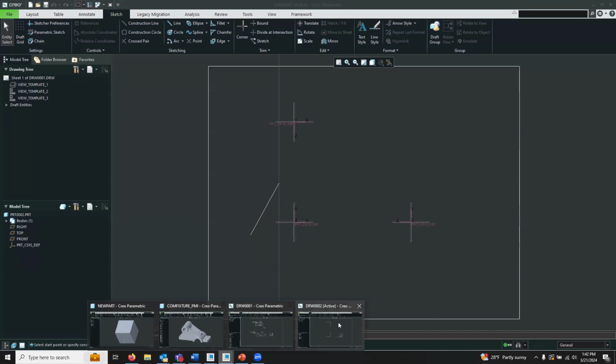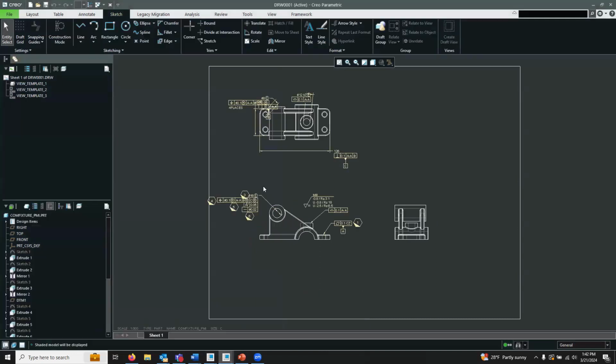So I'm now going to jump to Creo 10. And we'll notice right away that this looks much more like Creo Parametric. We can see that I have dimensions. I can hit tab to switch between them. I can also hold right click and switch to polar coordinates, so that would be an angle plus a radius. Many options such as snapping behavior are available right there in the mini toolbar.